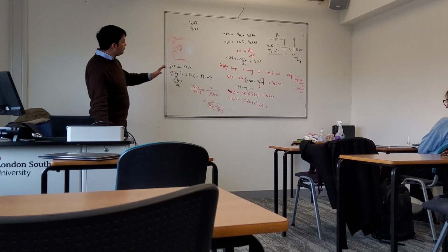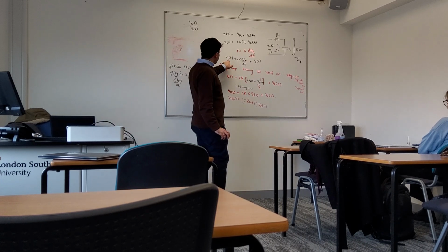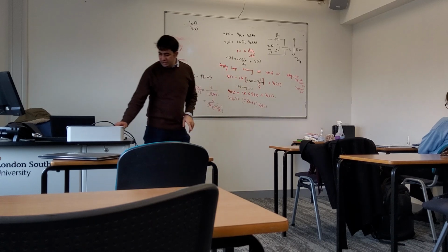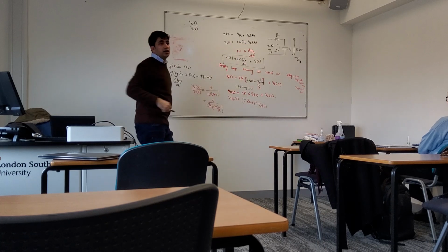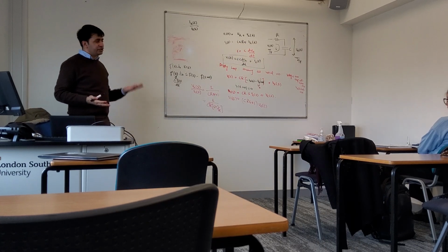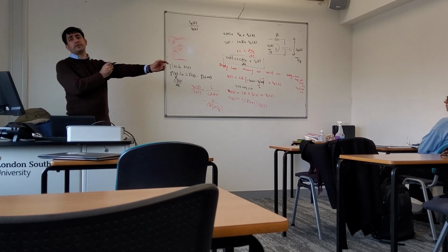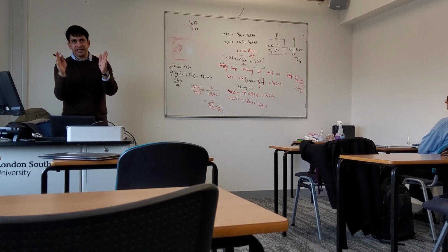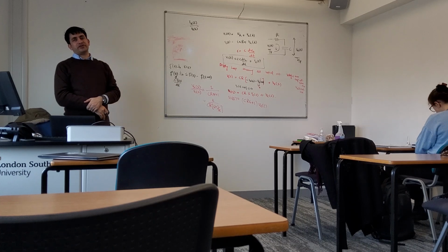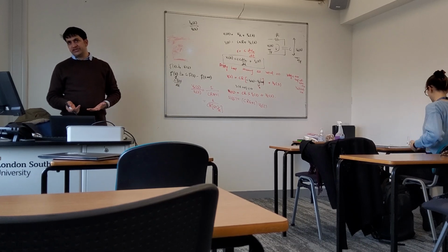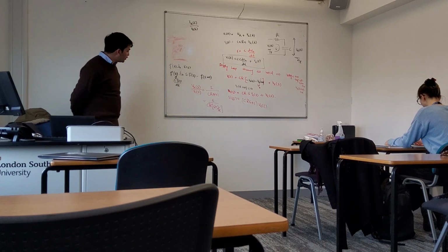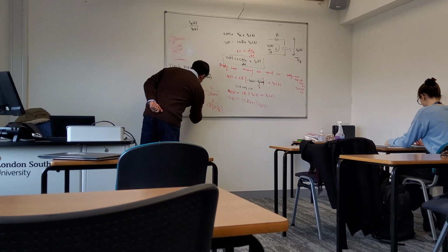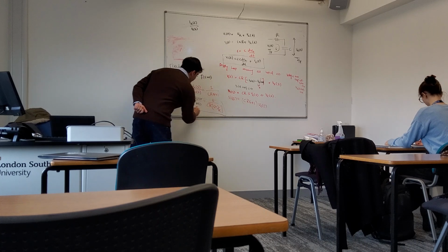So this is your transfer function for an RC circuit. Here you have a differential equation which we wrote from the circuit, and maybe in the exam you need to write it from the circuit, but it is also possible that you get the differential equation directly, and you just need to apply the Laplace transform by assuming zero initial conditions if you are asked to find the transfer function. So I have V2(s) by V1(s), and this gives me a transfer function.